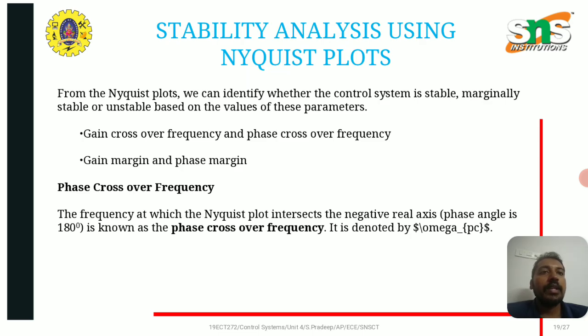Gain crossover frequency, gain margin and phase margin can be calculated using Nyquist plots. The frequency at which the Nyquist plot intersects the negative real axis is known as the phase crossover frequency.